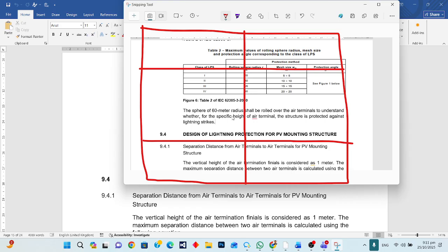So this software will be used to do the earthing calculations, and when we use it, we get the optimal options. Like with this type of option, we increase the spacing between the conductors, and we get the optimal step and touch voltages in the tolerable limit, and ground resistance in the tolerable limits. When the software is satisfied in that area, we will submit that earthing calculation to the client saying it is okay.